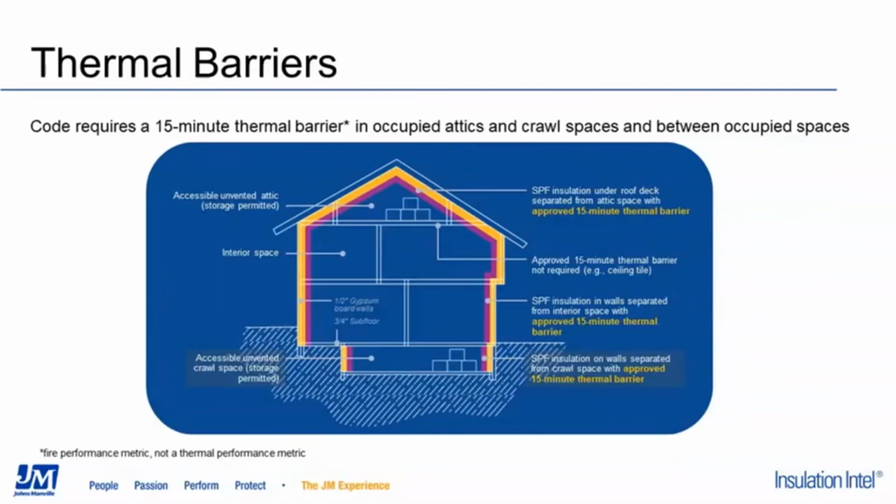The one thing that you have to be aware of is that any foam insulation burns. So once the product's installed, it needs to be covered with an approved 15-minute thermal barrier. And that includes the attics. If you're going to be storing anything up in that attic or going up there to do maintenance, that has to have it, along with all the walls on the interior and in the basement.